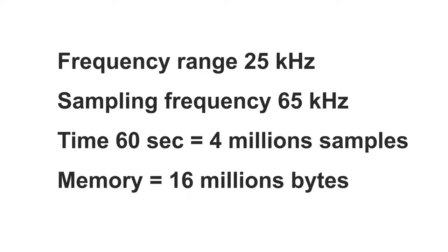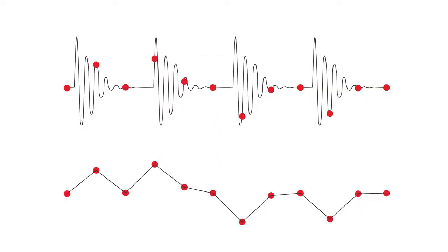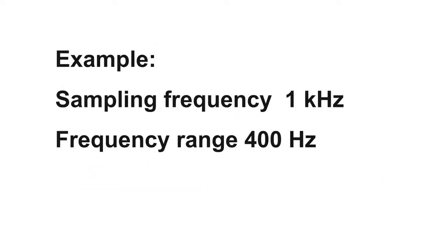You can argue that I should use a lower sampling frequency, but it does not work. We would have a long time between samples and we lose the shape of the signal. Additionally, the anti-aliasing low-pass filtering will remove high frequencies, but we need them. The natural frequencies of shocks are in the high range.